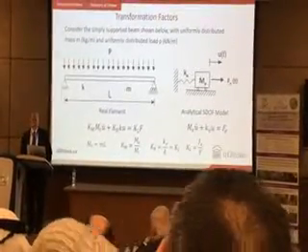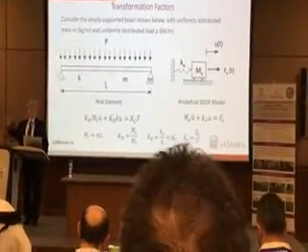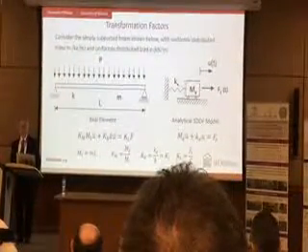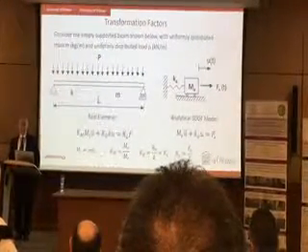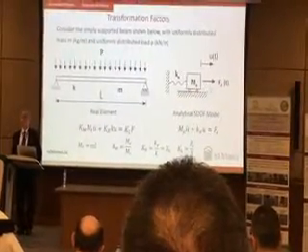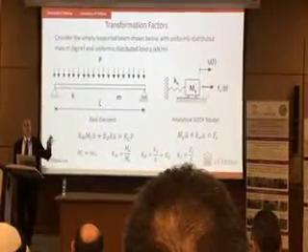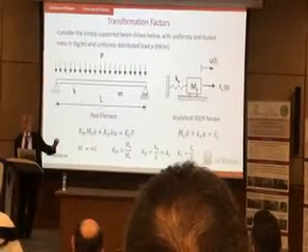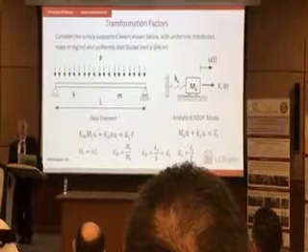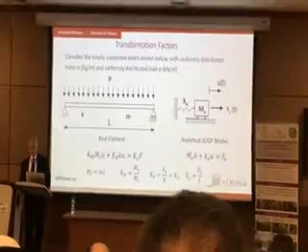But what we have is distributed mass. If I have a beam, it's distributed mass, it's not a lump mass. And if I have blast pressure, it's distributed load, not single load. So how do I go from this real element to single degree of freedom model? I have transformation factors. All I have to do is find mass of the real building or real structural element, multiply it by transformation factor for mass. I now convert it to this model.